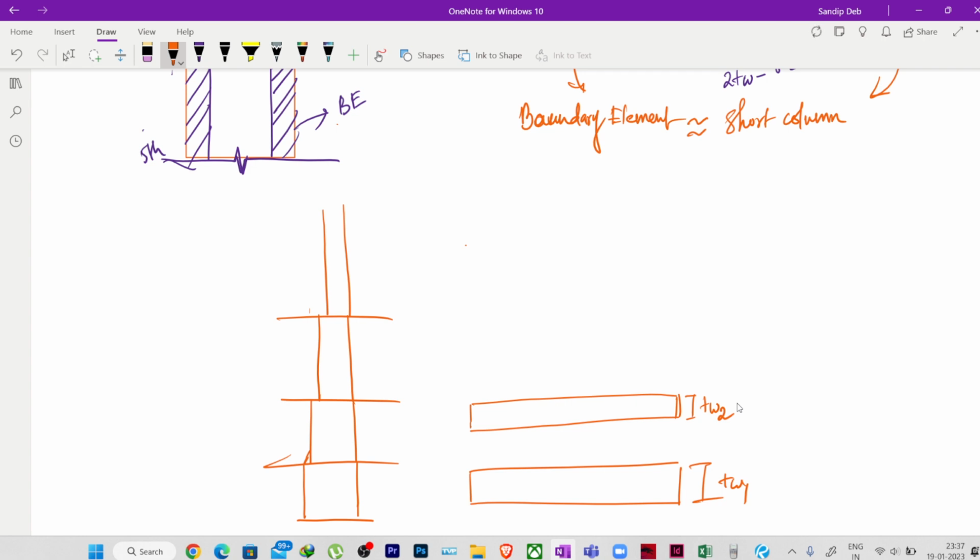So just have a look at IS 456, where the maximum slope is defined, or you can refer to SP 34 also. Based on that, we can decide the slope and reduce the thickness. Not only based on the slope of the bar, but first of all based on the moment capacity requirement.